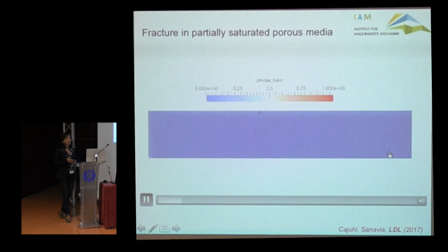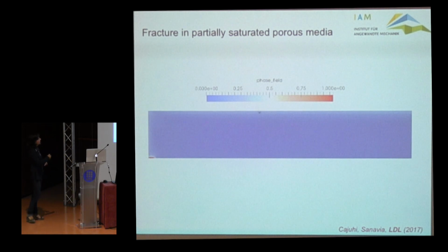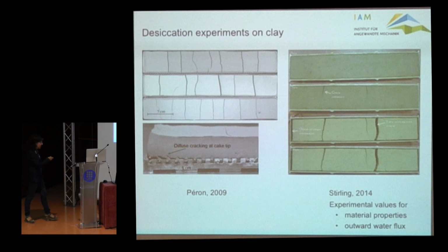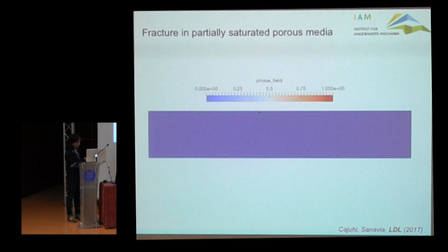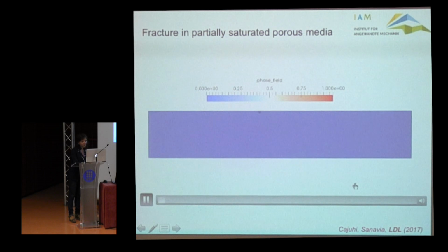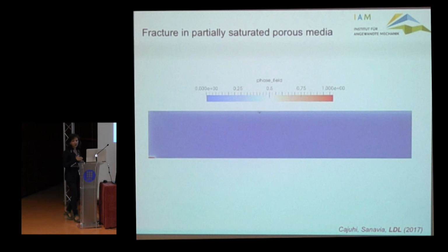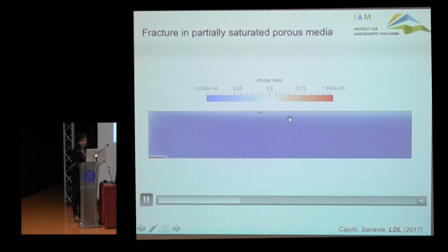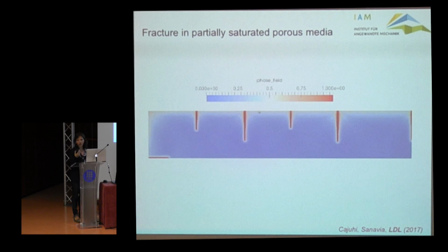This shows from the side what happens in the experiment. From the side, you have a bottom crack, which starts developing, and then, as the time goes by, there is a competition between this bottom crack, which is due to the fact that you have high friction between the lower base of the clay cake and the specimen, and then you start developing cracks due to the loss of saturation in the upper crust of the specimen, where the pressure becomes negative, and so you have desaturated conditions, and then there is a period doubling phenomenon where there are further cracks that form more or less halfway.